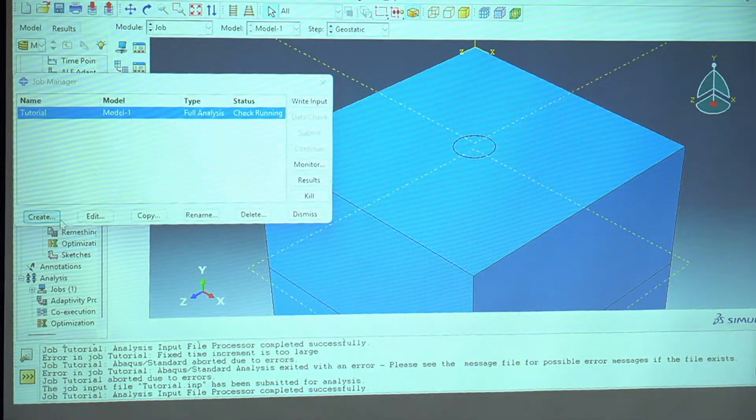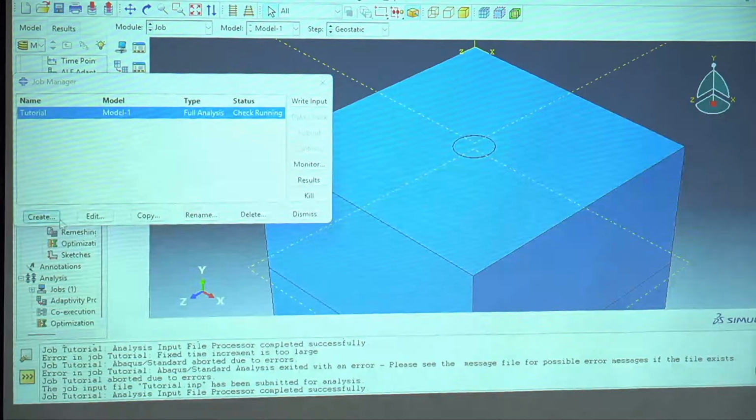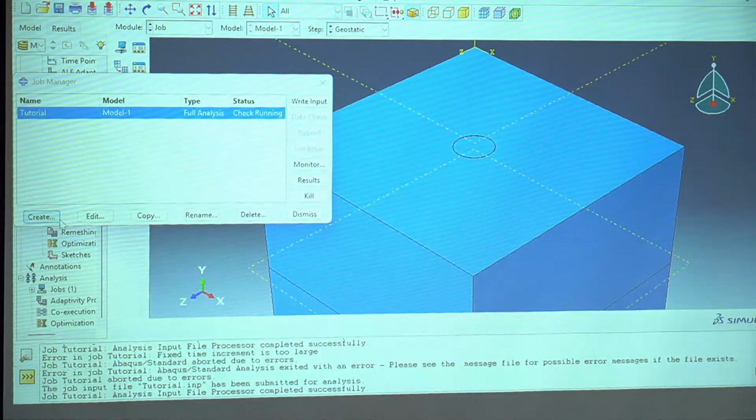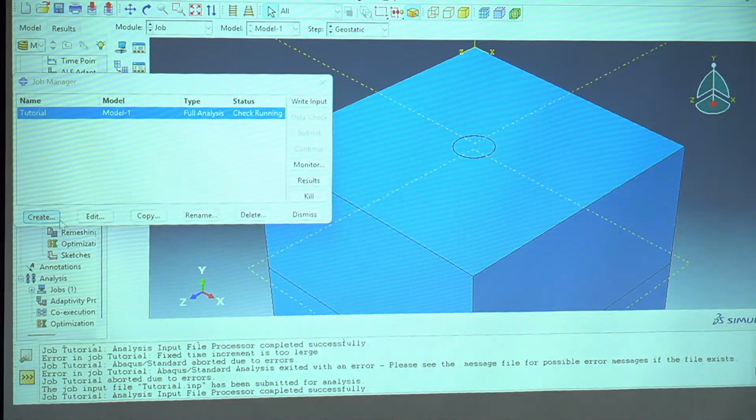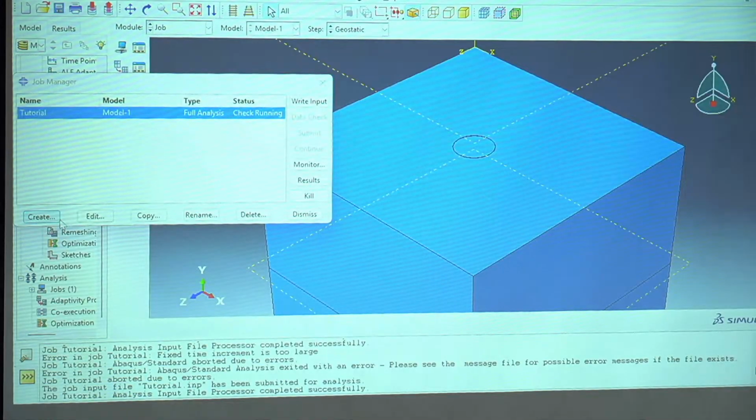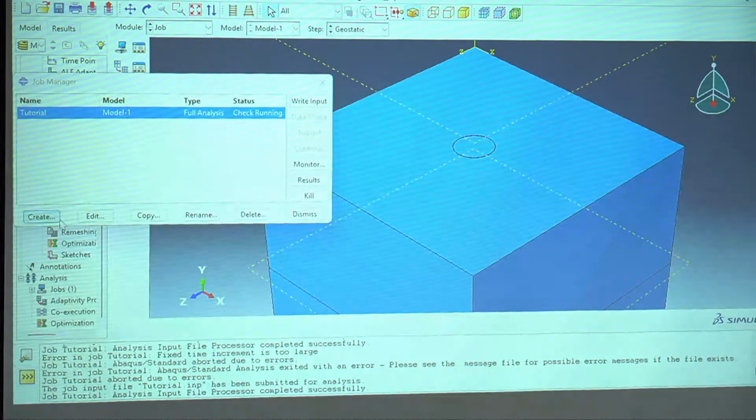So in your input file, for the pile and the soil interface, you created the master and slave surface, right? Yes, sir. Is the length of the pile and the size of the hole correct? Yes, exactly. It's 1 meter diameter and 5 meter pile. Yes, 5 meter. And the hole is also 5 meters. Yeah, there's something wrong. Even if this doesn't run, surely the other won't.